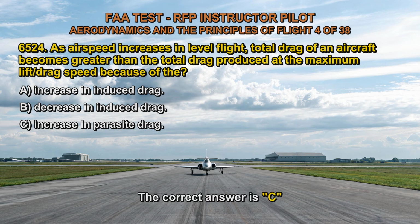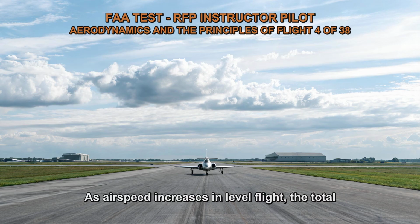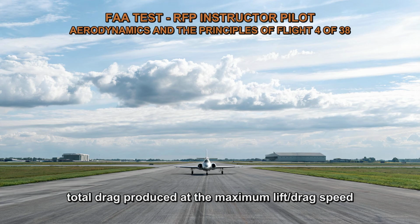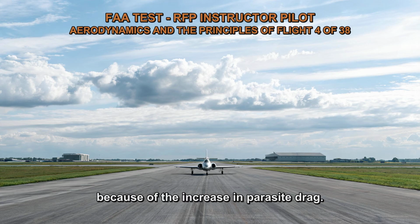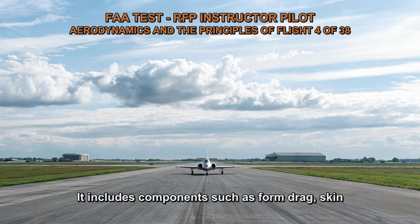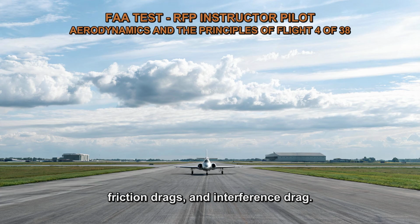The correct answer is C. As airspeed increases in level flight, the total drag of an aircraft becomes greater than the total drag produced at the maximum lift/drag speed because of the increase in parasite drag. Parasite drag is a form of drag that is caused by factors other than the production of lift. It includes components such as form drag, skin friction drags, and interference drag.